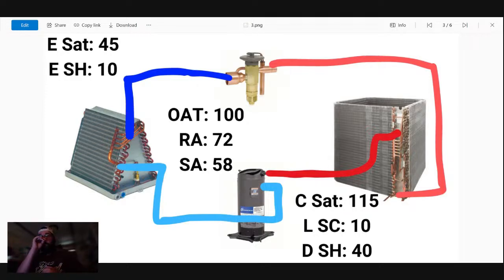And there are some systems that, because of the humidity issues in the space and just the overall design of it, they do run the blower at low speed, even in cooling mode. So don't let that be just an automatic, well, that's only for heating or such, because I've heard that before.